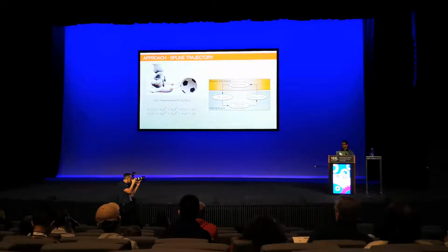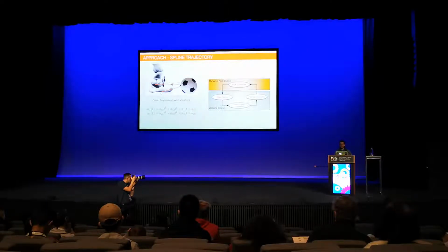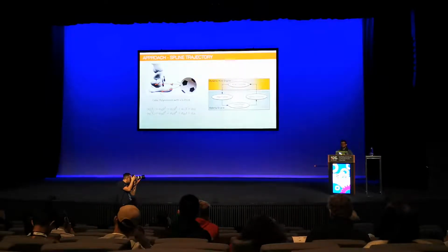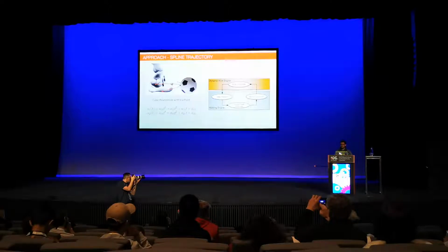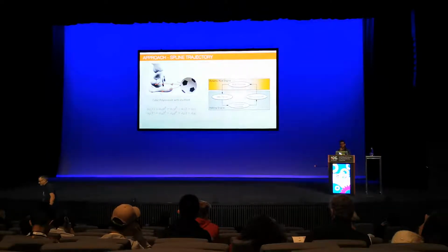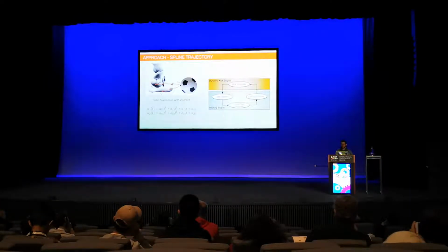As the robot is walking, the kick trajectory generated is constrained by the goals of the step planner. X start and X finish are two positions given by the step planner. The kick motion generated is these two points and then a via-point that allows the robot to reach the point of contact with the ball to generate kick motion. So rather than allow the step planner to interpolate between XS and XF directly, the kick controller stretches out the via-point such that it allows the robot to kick the ball and then reach the endpoint of the step planner request. So basically, the via-point could be put at any point in 3D space, and the kick trajectory interpolates between those points, which essentially generates the kick motion.